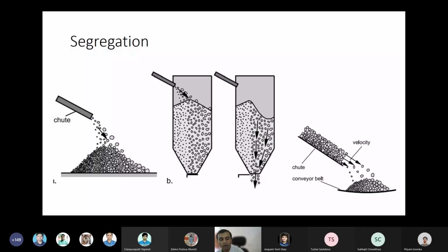When it flows off, obviously the velocities of light density particles and heavy particles differ. Both are discharged at the same velocity from the tube, but when they come outside, the way they settle, carry velocity and move depends completely on the surrounding fluid conditions. So you will see the fine particles fall at one place and big particles fall at another place.